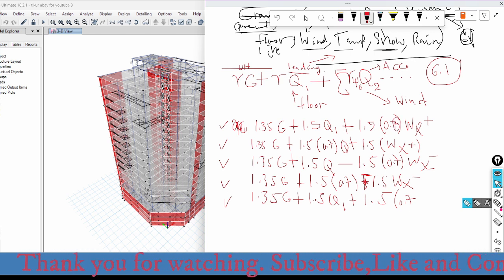Sorry, this one is what? It is 0.6, and this one is 0.7, because it can be taken from the code. The psi value for wind is 0.6, and the psi value for variable load is 0.7. So psi 0 for live load is 0.7, and psi 0 for wind is 0.6.